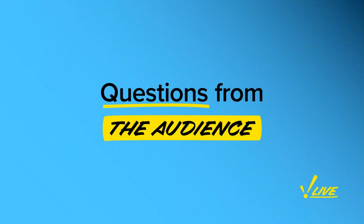We're now going to go to our Q&A section. Question here is from John. It says, does Ignition support Phoenix Contact RFC 430? So Ignition's driver set is the Allen-Bradley Ethernet suite, DNP3, Modbus, BACnet, Omron NJ, Omron CJ, Modbus TCP, Modbus RTU over TCP, and we have a couple specific oil and gas drivers and a TCP driver. So there's not a specific Phoenix Contact driver. However, if that device supports Modbus, of course, we can connect to it. Otherwise, we might have to look at a third-party OPC server for access to that data.